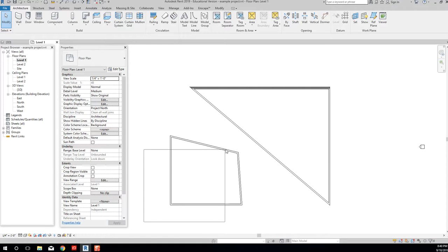You see how I'm touching all those things, but they're not being selected? It's because with this type of selection workflow, I have to select an object in its entirety before it will select. So in general, the bottom left to the top right, which means I have to get below that object and go above it.